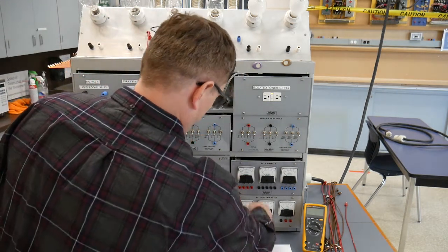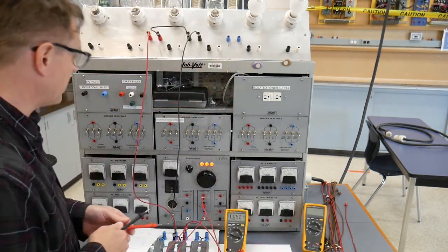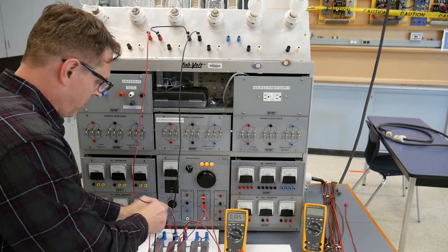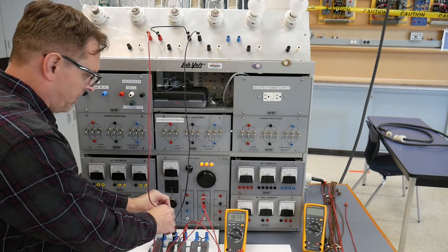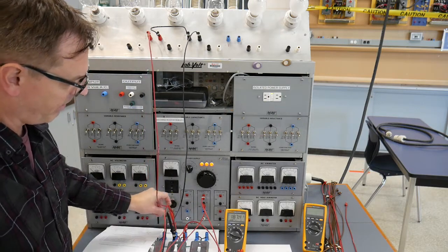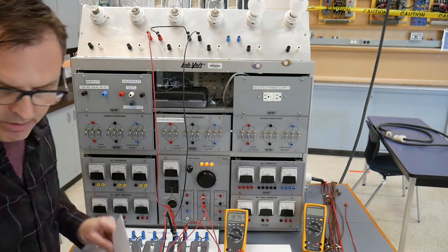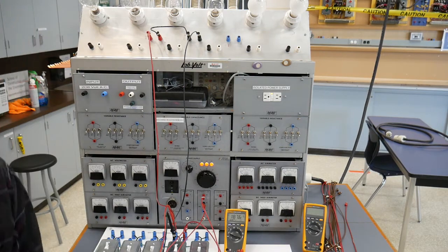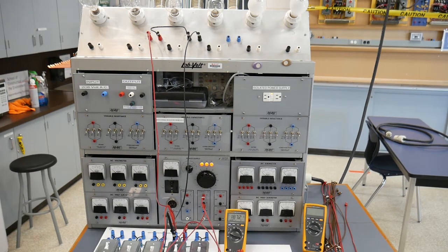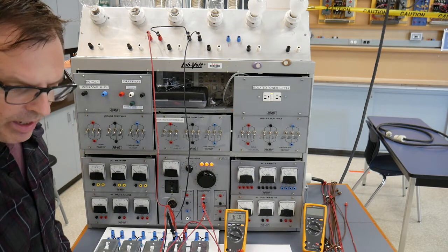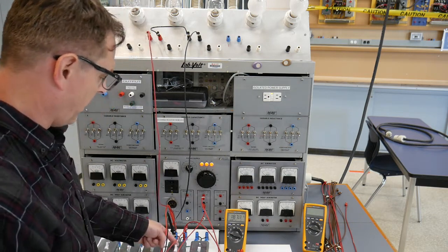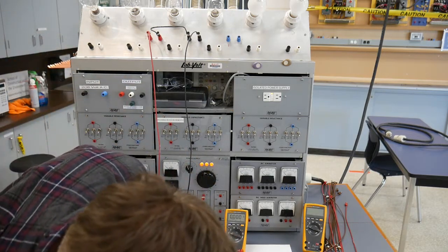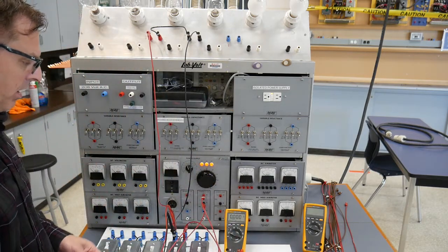So with that switch closed and these cone heaters warming up, we're going to measure from line to line on the output side. And we're going to see we've only got 187 volts output here. That's the maximum we're getting. 187. Okay, and the switch terminals A1 to B1 with the switch open. So I shut that off. With it open, I have 0 volts because we're on the other side of it. I'll go over this in the Learning Hub.